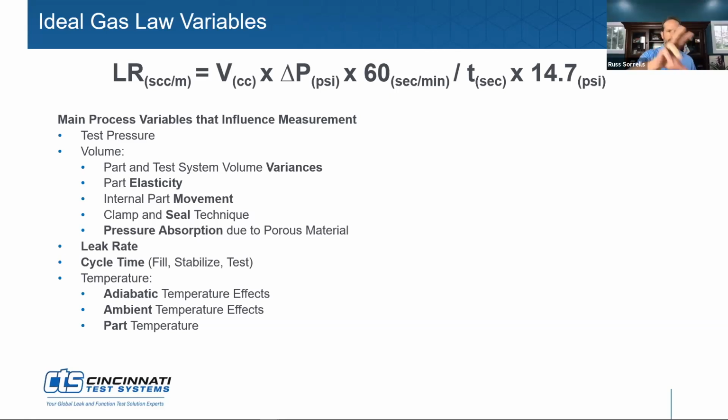Yeah, as you look at this list, I always tell customers leak testing is very simple. I mean, obviously, it's complicated. Look at this formula, and there's a lot of things going on, but it's simple if we just remind ourselves that anything that affects the pressure that we are measuring, the pressure in the test circuit, because oftentimes we forget the line that goes from the instrument to the part, which could go through some valving along the way, any pressure change in that is going to cause a challenge with the repeatability of our application.